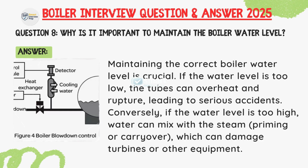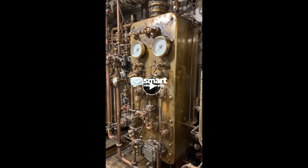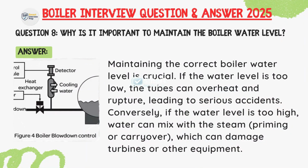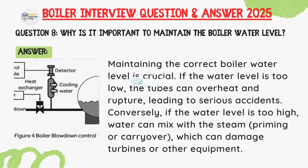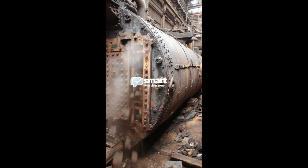Question: why is it important to maintain the boiler water level? Answer: maintaining the correct boiler water level is crucial. If the water level is too low, the tube can overheat and rupture, leading to serious accident. Conversely, if the water level is too high, water can mix with the steam, priming or carryover will occur, which can damage turbine or other equipment.